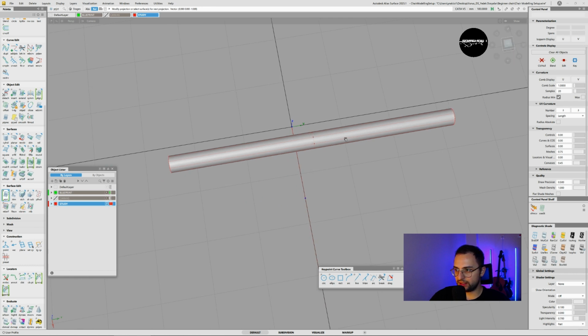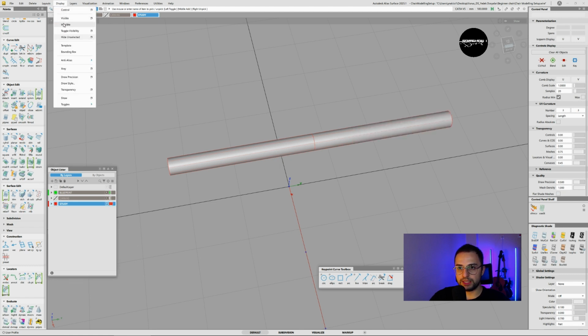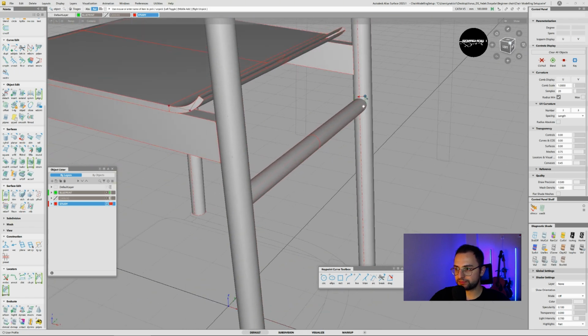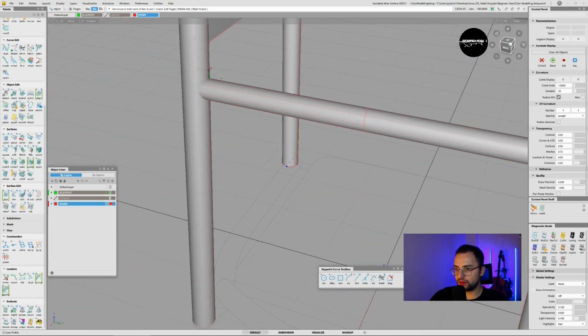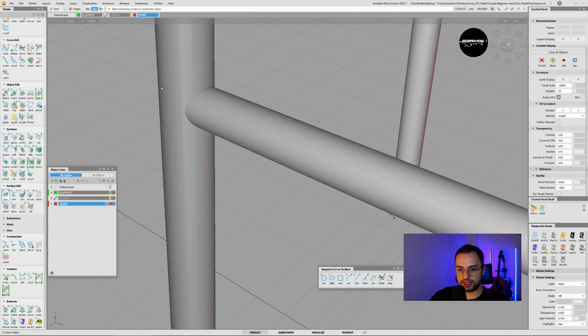This is called curve on surface, which means this is projected. I'm gonna delete the half of it because it is duplicated already since we have the symmetry here. So I close that one, trim this one, keep, and I don't need this one, delete. You see, when I open the symmetry tool, yeah, we have what we need. Visible. Yeah, let's select this one, intersect with this one, and trim.